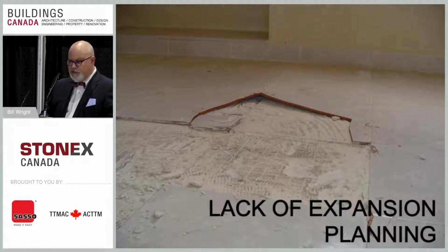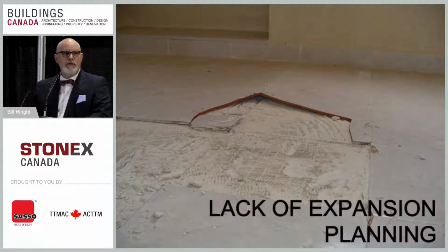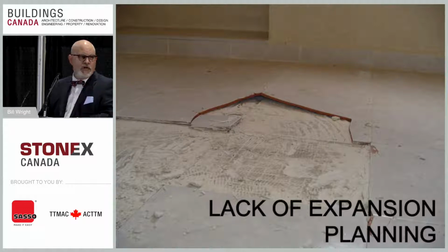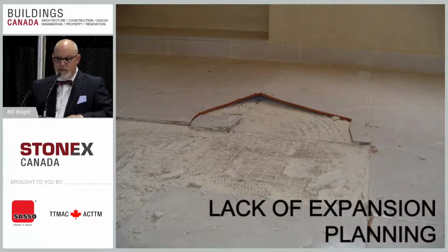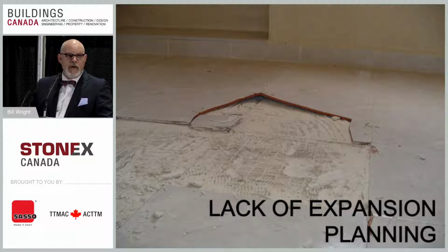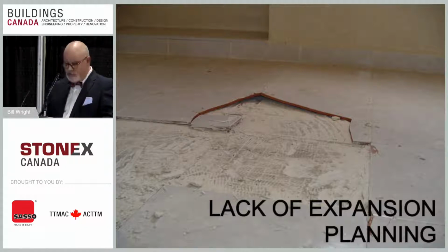I had to go to a job site, one of the 30th floors of an office tower downtown. It was a herringbone pattern, no expansion joints. On a big windy day, the building moves pretty good, and in no short time there was some cracking and tiles breaking. And my first question to the contractor was, "Why didn't you put the expansion joints in?" And his response was, "The specifier didn't want them because it would interrupt the pattern." And we look at the floor, and I don't think that the owners were too happy with the way things were looking. So please don't skip these.